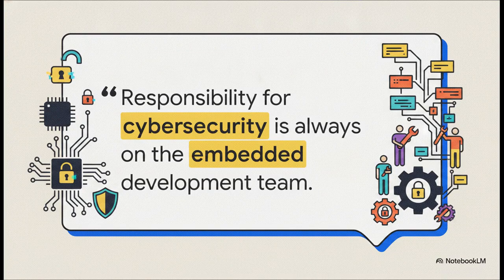Now, security. This always starts a huge debate, right? But it's vital to keep this role in mind from Ivan Kubara, an embedded team lead. Look, a highly optimized FreeRTOS system naturally has a smaller attack surface and fewer vulnerabilities by design. An embedded Linux system is massive and complex, which inherently introduces more risk. But at the end of the day, the human element, securing the device, patching it, designing a secure architecture, that responsibility sits squarely on your team's shoulders, regardless of which OS you choose.